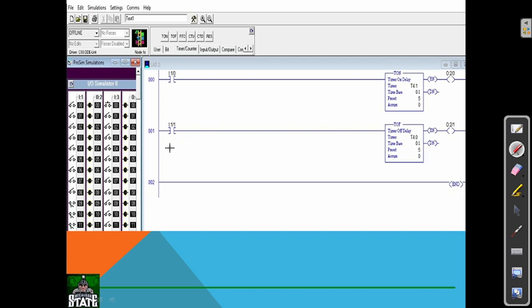In this process, see, if I switch off this switch, for example, this is the motor. If I switch off, the motor will not suddenly turn off, because I am using this off delay timer. If I switch off, then this off delay timer will start running. After 5 minutes only, the motor will turn off. That is called an off delay timer.